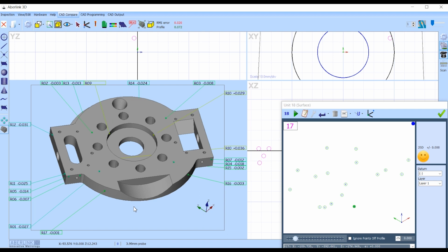Okay, what I'll do is I'll probe this, the slot, which a feature does fit in there. We'll see how accurate that is. And the cone, we'll throw a couple of points on the cone. We need a couple to make sure that it's within tolerance. And also our plane. We can see that the plane has been wire cut, so it's going to be a little bit out because it's a secondary operation. I think down the bottom here that it's fine.